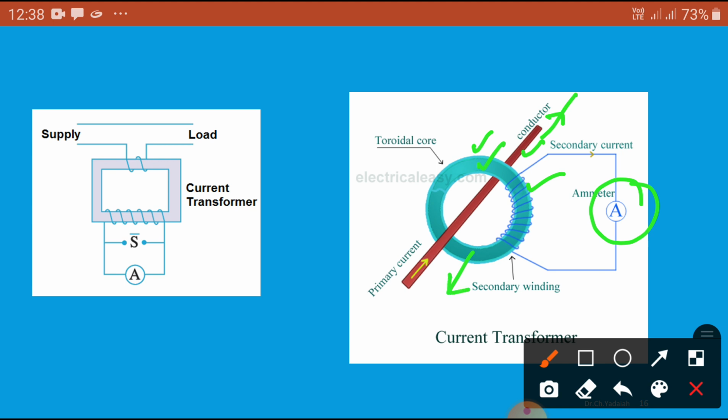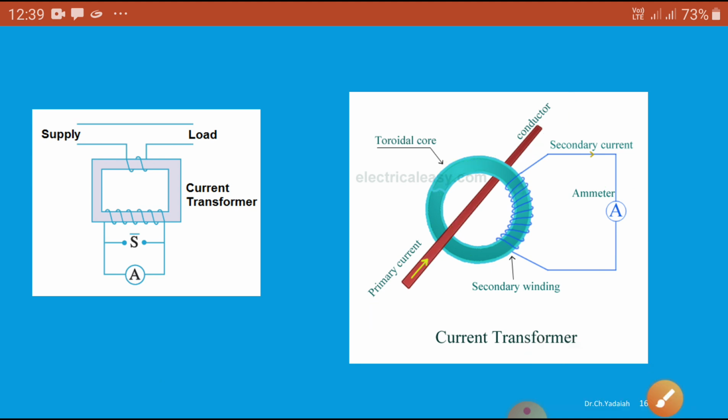So based on this, in the practical field, whether you are going with a single conductor, here the primary conductor simply goes through the outside, and sometimes the winding is a single turn, 2 turns or 3 turns, provided in the core material. So this is the primary. Then different applications have different current ratings and CT ratios, and correspondingly the current flows in this.